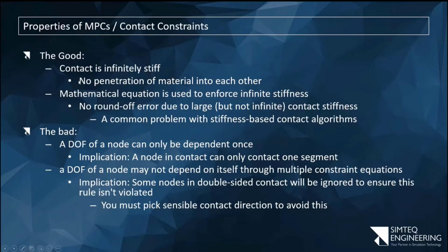Okay, so in other words, the contact is infinitely stiff. The material cannot penetrate into the other material. So this is not like if I press an indenter into another material. In this case, it'll do the exactly correct thing, because the nose of the one will deform the mesh of the other. In other words, the indenter will cause that penetration as you expect, but the material isn't diffusing into the other one, because that's what contact penetration would have meant. So the one material kind of diffuses into another, which is not really physical. It's a mathematical equation that's being solved.